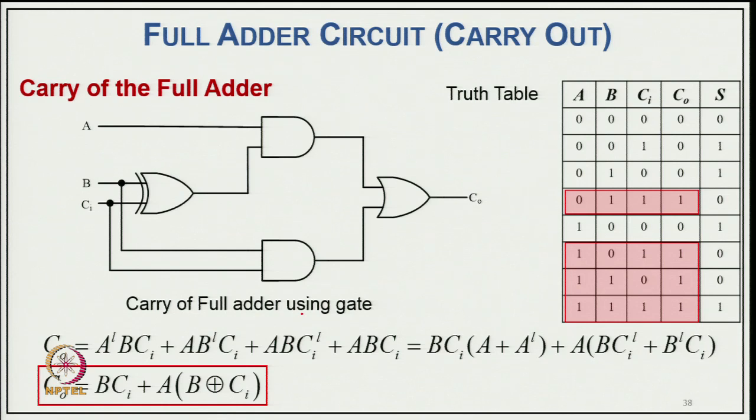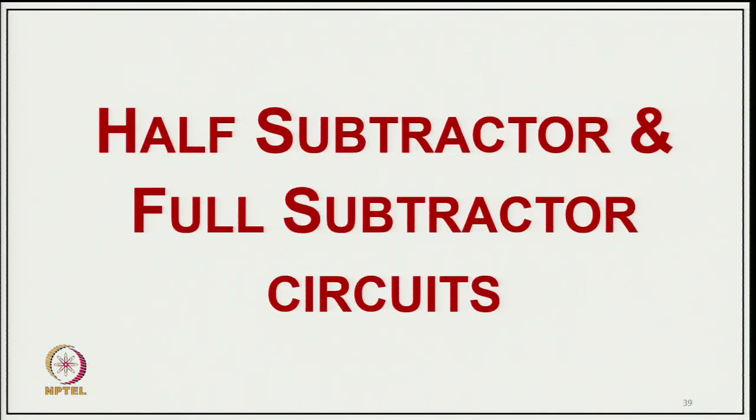So, this represents this term, and then the second term, which is B C I, represents the second expression, and both expressions for sum go through an OR gate. So, this goes to the C output, which you can call the carry output of the full adder. That is the way we represent this full adder by logic gates. There may be many other ways also, but this is one way to design the full adder.